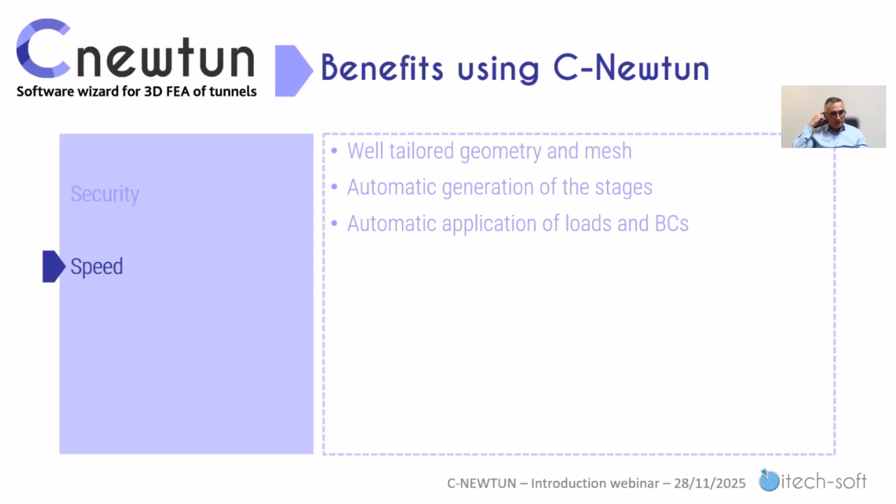We are proposing tools so that we are optimizing the mesh, so number of nodes, size of the matrix, and reduction of the calculation times, and also with this permanent regime or steady state condition, we do not calculate excavation stages if they are not pertinent for accessing the settlements, for example.